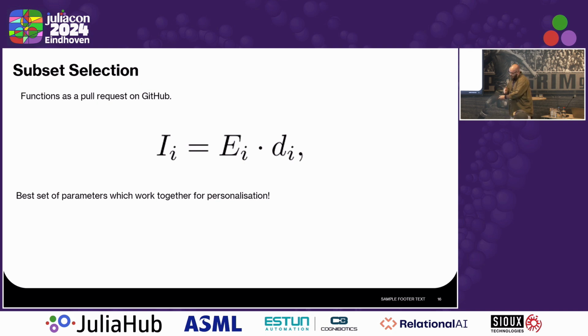So the idea behind that is saying, if you've got a response surface for a set of outputs, you need to make sure that the influence of the parameters is orthogonal. So if I stand behind somebody and we both throw a ball in the same direction and somebody turns around, you've got no way of understanding who threw a ball the furthest. So you need to be able to differentiate between the parameter effects as well. So them just being influential doesn't always cut it.